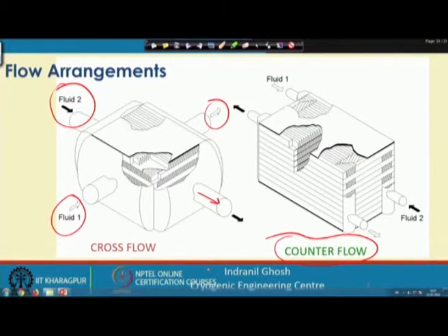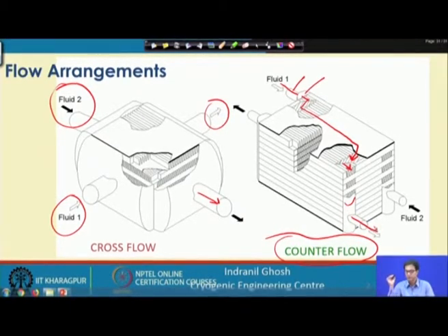we have seen that we need a distributor to distribute the flow. I mean, from where it is coming, this is the nozzle, then we have the header, then we have the distributor to allow the flow to come in and then get distributed like this. Finally, this moves out from this distributor fin assembly, and finally it is getting collected to this header and the nozzle and moving out.